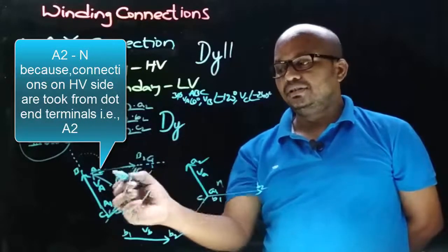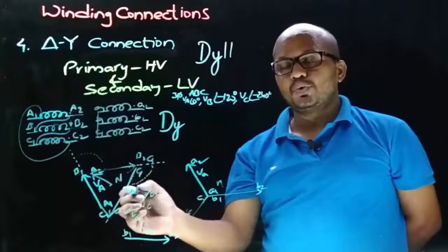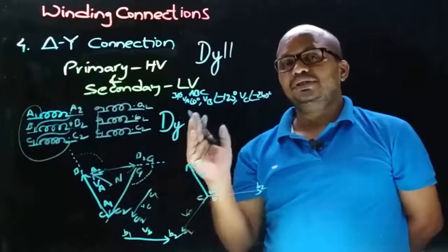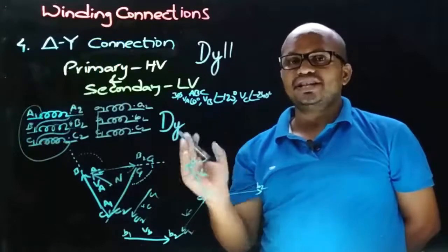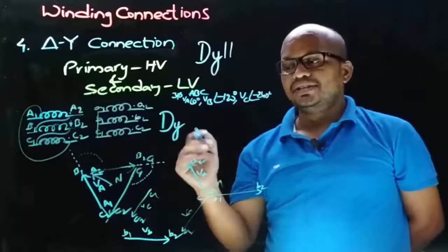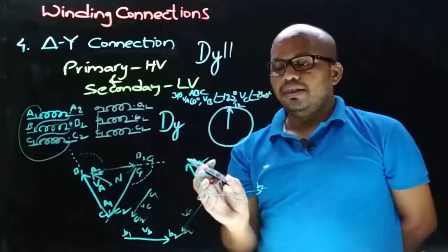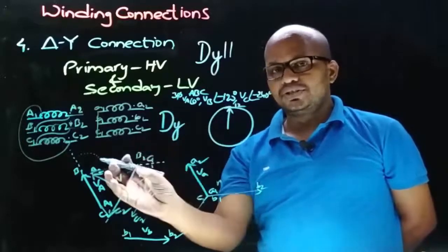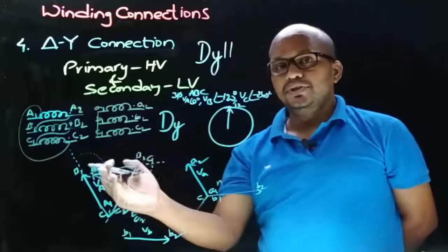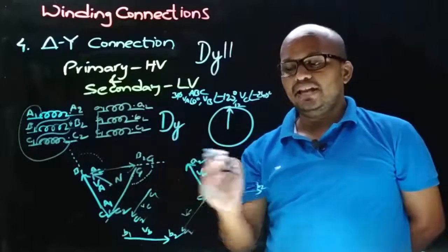And it is studied that the HV winding phase to neutral voltage is represented with the minute needle in the clock and is always taken as a reference. So it is always shown pointing towards 12 on the clock. And now to know the numerical, let's superimpose this diagram on this diagram and observe the phase to neutral voltage of HV winding and LV winding.